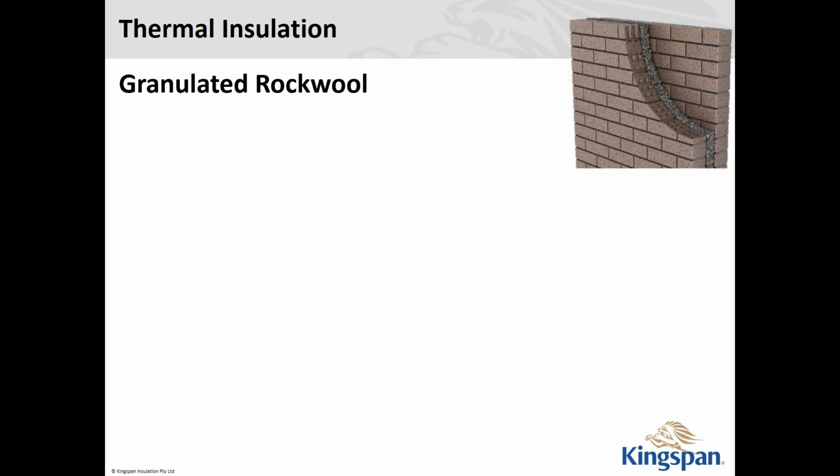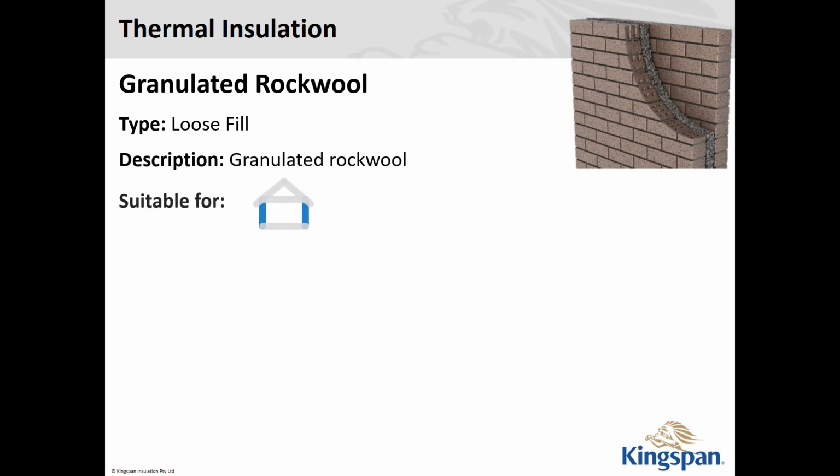Now, if you had a double brick cavity wall and you needed to retrofit, pumping in a cellulose material would probably be the only solution there. But there is a graduated rock wool. It's meant to be encased with little bits of silicone, so you don't get water ingress from one side to the other. So mainly between double brick leaf cavity walls it would get used, and it's the only product that really can be retrofitted into double brick cavity.